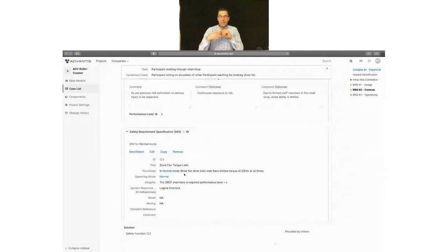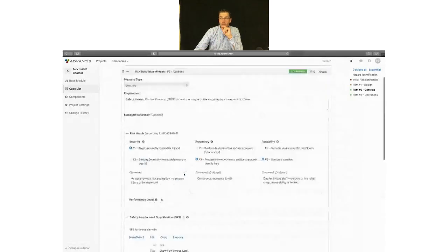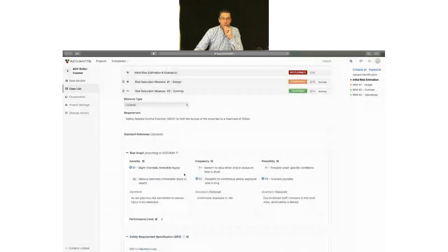And he gets this specification, and with this specification and his skills, he knows what to do. When I tell him, look, I need a VFD, a drive, frequency drive with a torque limiter, and it has to have a PLC rating, try and find one. And by the way, the limit is 20 Newton meters. And that 20 Newton meters I put in purposely because that is important.